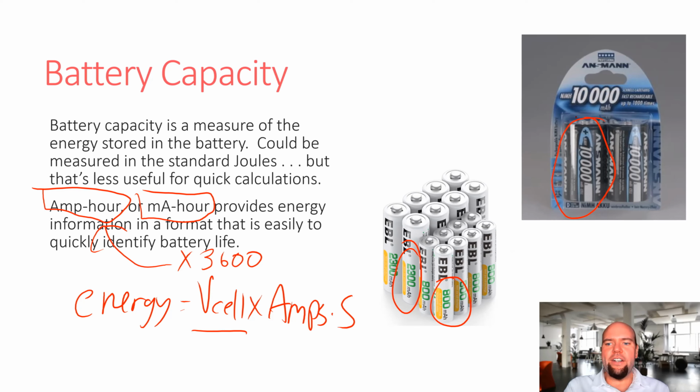But there's a big difference between a D battery and a AA. A D battery is typically 10,000 to 12,000 milliamp hours. This is a rechargeable one, I believe, shown here, because rechargeable ones are often the only ones that tell you the milliamp hour rating, because that's where it's really relevant. But a normal alkaline D battery is going to be 10,000 to 14,000 milliamp hours. So that's a fair amount. A single D battery could provide 10 amps of current for an hour. That's impressive. Or 14 amps of current, even, for some of them.